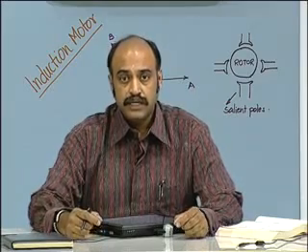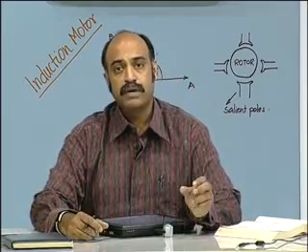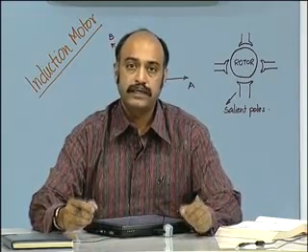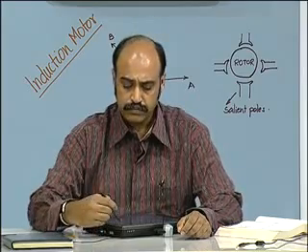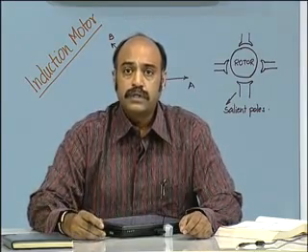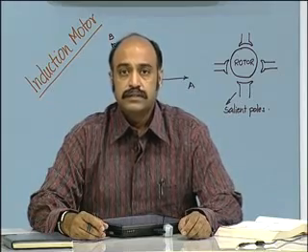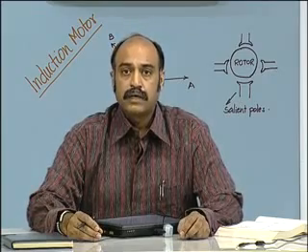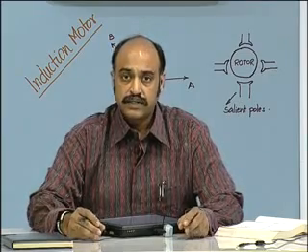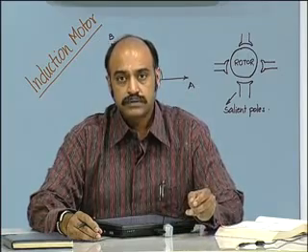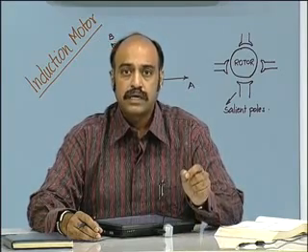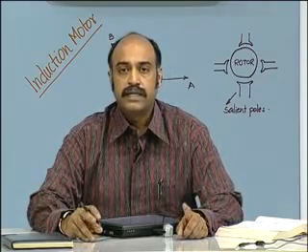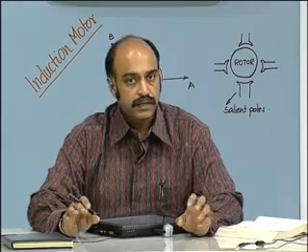But the important concept now is that how do we bring about a relative motion between the field in the motor and the rotor conductors. Now, to achieve that, we use the three-phase source. So in the three-phase source, we have three sources wherein they have the same effective amplitudes, however they are 120 degrees apart in time.